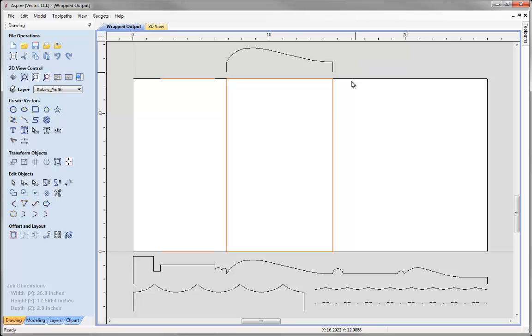Essentially what we're looking to do though is end up with just the bulging section of our profile with vertical lines on it that make it the correct height from the center of the spindle, and then these vectors here which are just going to give us the octagonal shape at each end with this lower vector, and in the middle at this point here with the higher vector. That's why we did that measurement earlier, to make sure that we'd get the right curvature when these were unwrapped.